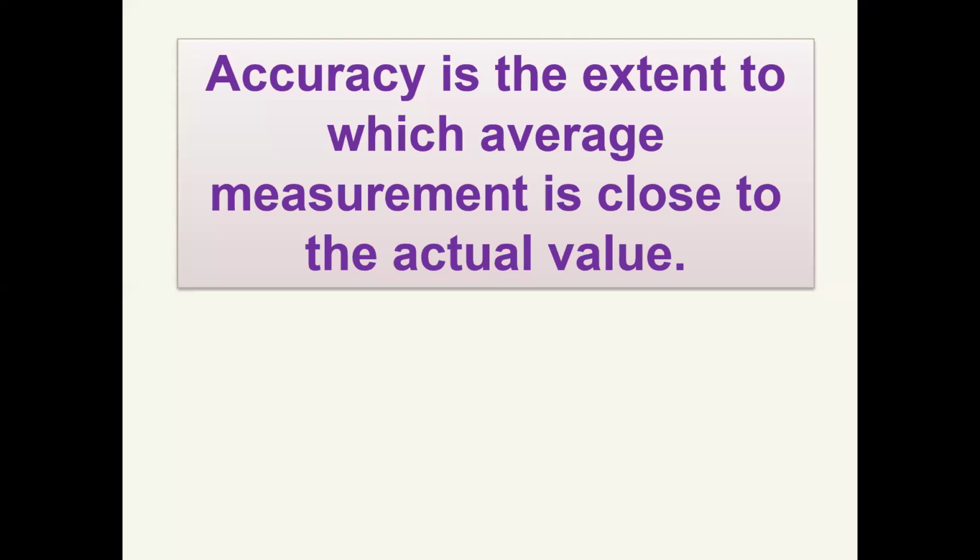Just for example, your watch is 5 minutes ahead and you can't fix your watch. It means it's a systematic error. You can adjust it, and you say, okay, fine, whatever answer you are getting, subtract the error from it. So we have a concept: random error can be reduced by averaging. Systematic error cannot be reduced, it can be adjusted.